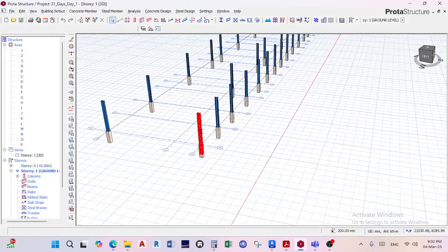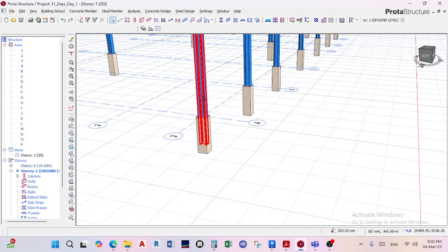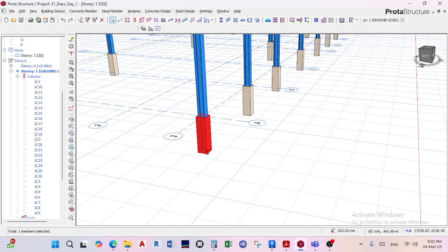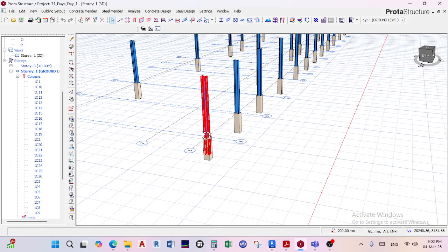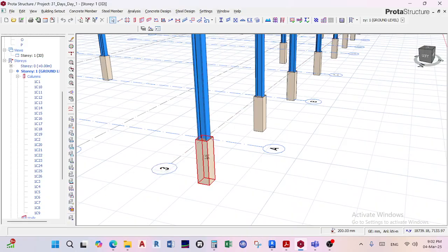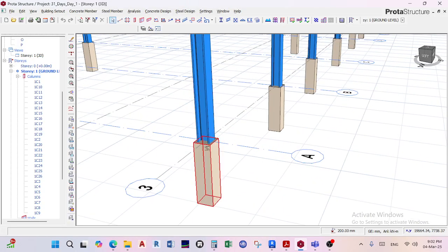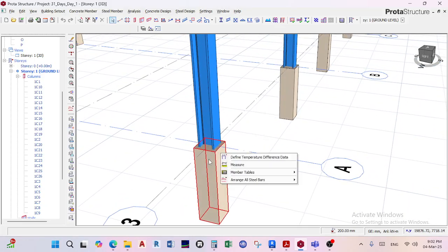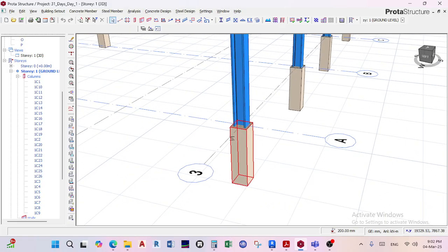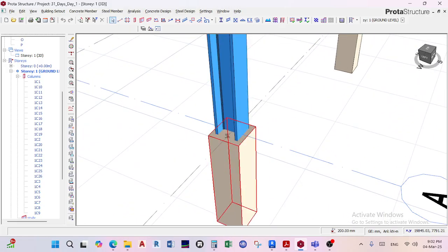So here we've got a situation where the steel column is getting into the concrete column. This is not how you model or how you design it. It's not the correct way. Why? Because you need to place a connection here, a base plate, right? By means of anchorage. In the future, maybe we'll get to learn about that. So this is not a perfect connection.